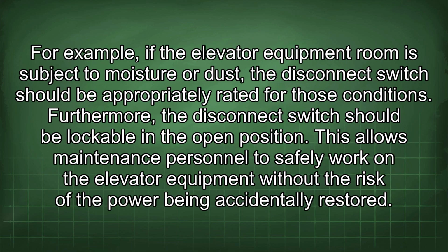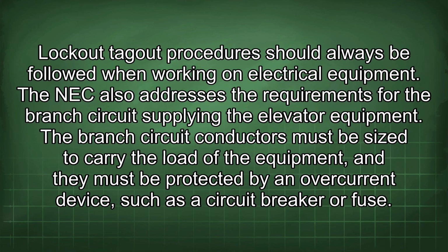For example, if the elevator equipment room is subject to moisture or dust, the disconnect switch should be appropriately rated for those conditions. Furthermore, the disconnect switch should be lockable in the open position. This allows maintenance personnel to safely work on the elevator equipment without the risk of the power being accidentally restored. Lockout-tagout procedures should always be followed when working on electrical equipment.